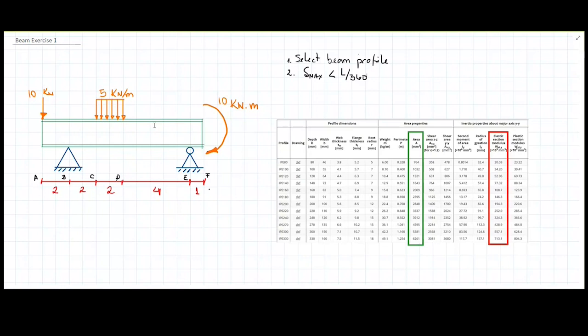In the case of a shaft, I mentioned that the deformation is going to be very dependent on the elements mounted on the shaft. For example, bearings have a very strict deformation restriction, meaning that the requirements for deformation of a shaft are way more exigent than for structural members. And on the shaft you may have, for example, installed gears.